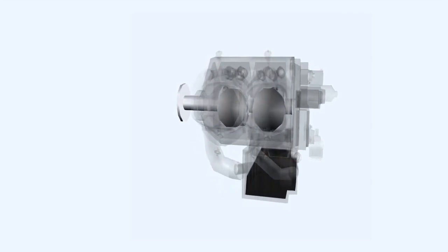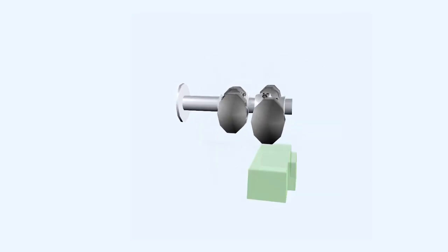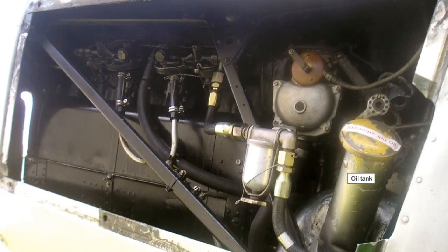For instance, a plain hydrocarbon oil, under the conditions of high temperature which it will endure inside the sump, will start to crack or break down, and also combine with some of the free oxygen remaining from the combustion products. Finally, the oil supply is limited by the sump capacity. The dry sump system overcomes these problems by storing the oil in a remotely mounted tank.